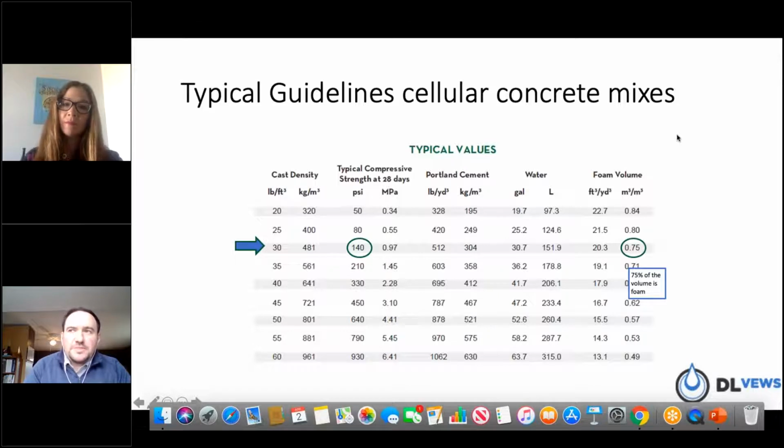But if it is the opposite and it's a good amount of water and it's become a nuisance, there have been scenarios even recently. We just did one out in Buffalo, New York, where there was a lot of water coming into the annulus, and we were able to displace it and get rid of it utilizing a cellular grout that is actually above the weight of water, density-wise.